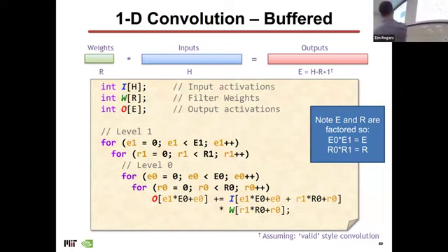With basically weight stationary on each inner loop, right? So now you wait stationary at the L0, try to maximize locality in your L0, and then once you sort of overwhelm the size of your L0, go back out, load in another big chunk that goes to the L0, and then do it again. This is sort of a classic tiling mechanism.